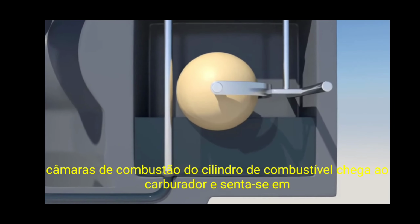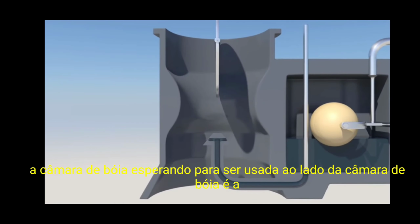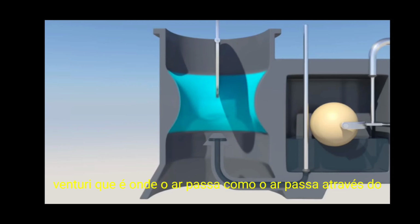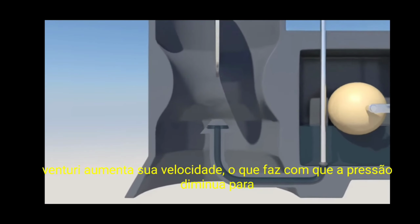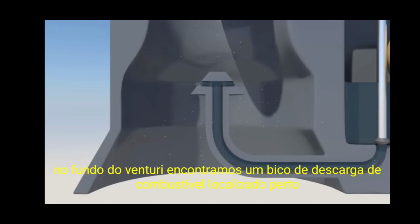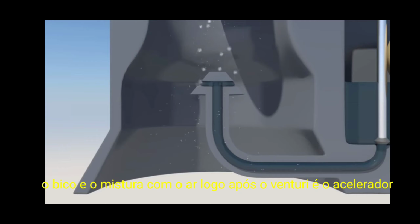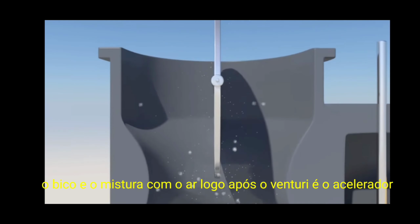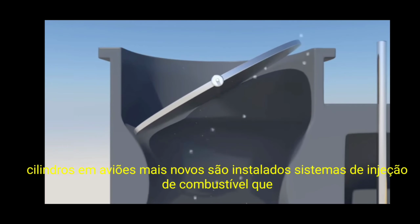Fuel arrives at the carburetor and sits in the float chamber, waiting to be used. To the side of the float chamber is the venturi, which is where the air passes through. As the air passes through the venturi, its velocity increases, which causes the pressure to decrease. Towards the bottom of the venturi, we find a fuel discharge nozzle, which is located near the area of low pressure. This draws the fuel out from the float chamber through the nozzle and mixes it with the air. Just past the venturi is the throttle valve. This controls how much of the fuel-air mixture is being sent to the cylinders.